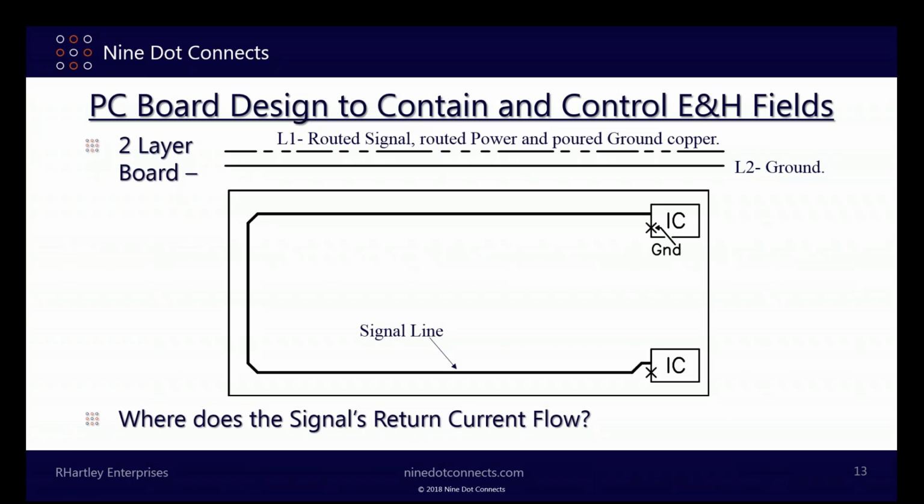If the distance between those 2 X's across the plane was 1 inch and the distance around that trace was 20 inches, the current will take the 20-inch path and will ignore the 1-inch path at frequencies above a few hundred hertz. The reason is that's the path of lowest impedance, the path of lowest inductance, and the path of greatest capacitive coupling. And that is the path the current will always take in a situation of this type.